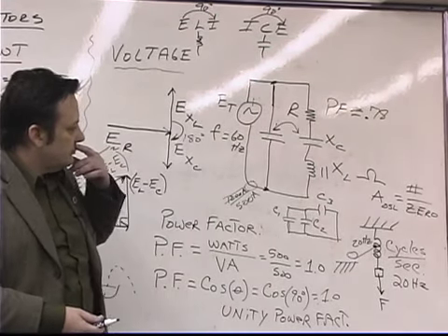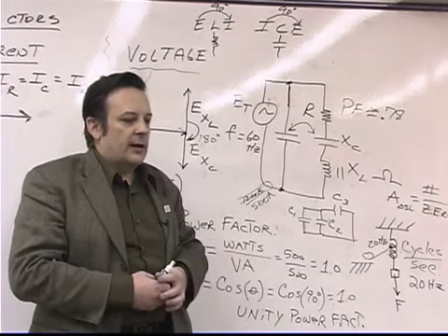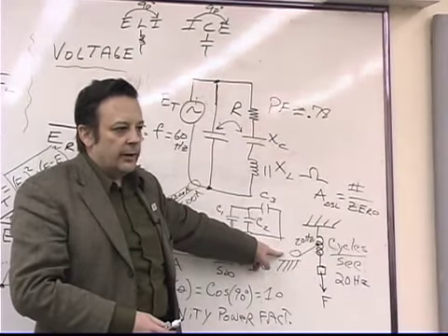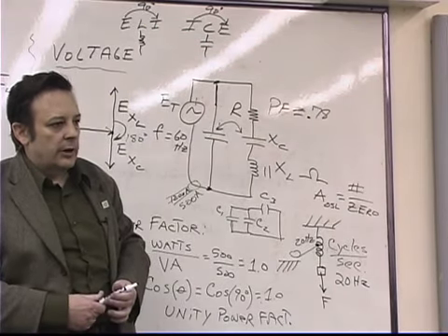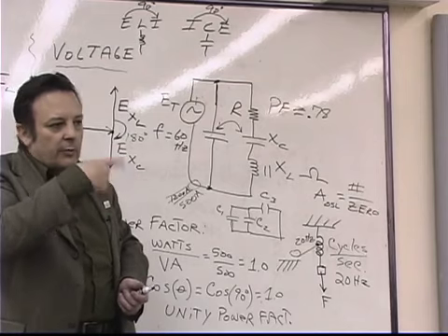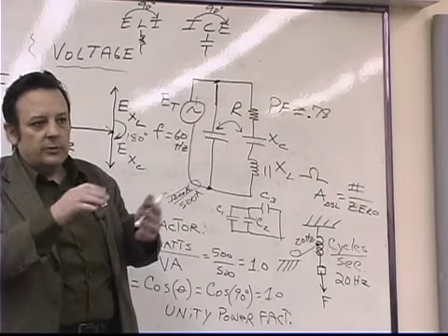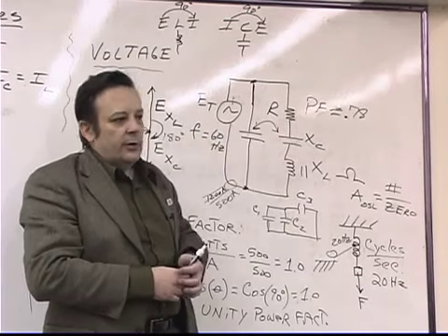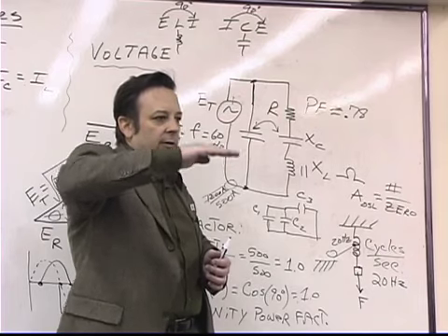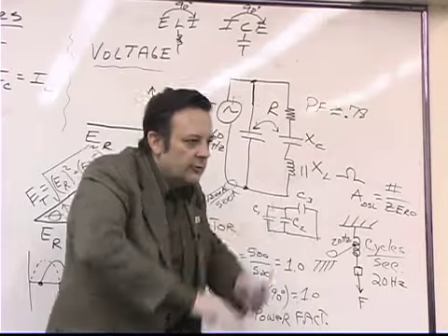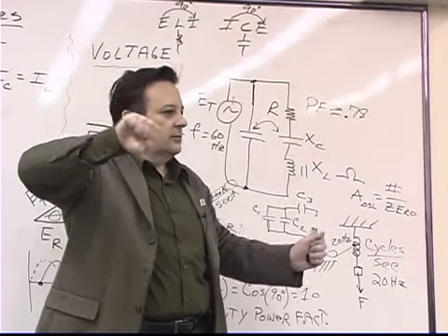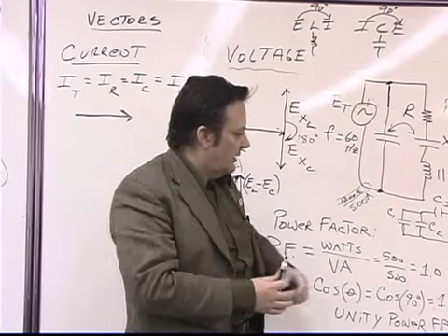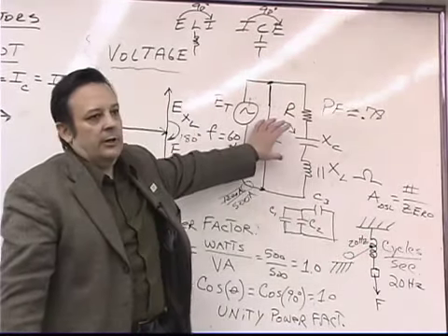Okay? Did you have a machine that just did that and made energy? Yeah. I actually took a physics class where we had a little pulley that was hooked up to a motor. It was like a sewing machine motor, right? And so we could determine how fast the pulley was going to spin around by turning a knob, which was connected to a variable speed drive. And so as a result, we could change the frequency that we yanked on the spring. And it's very interesting because you'll see the springs start out like this, and then when you hit the natural frequency and you're tugging on it, it starts doing this, and then all of a sudden the spring's just stretched out and it's effectively non-operable.